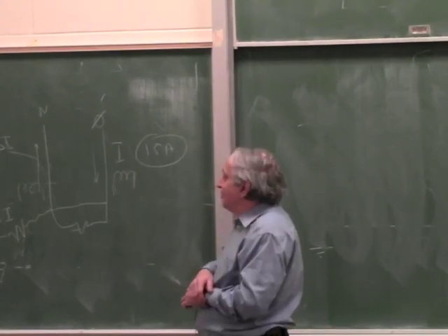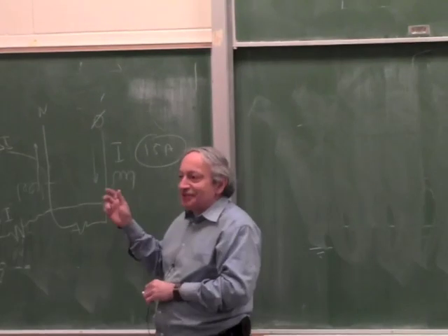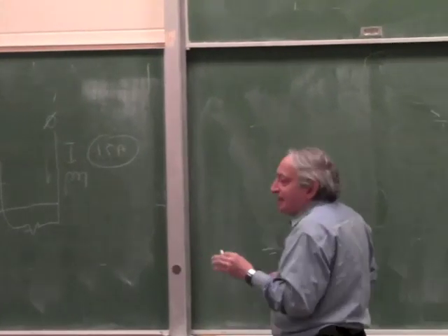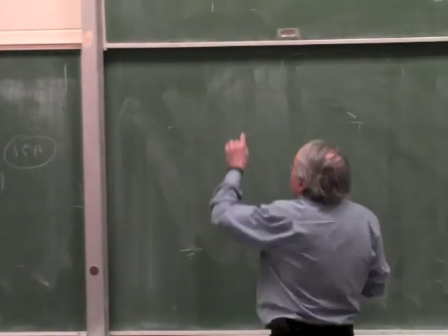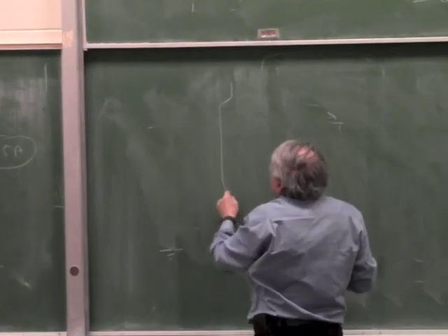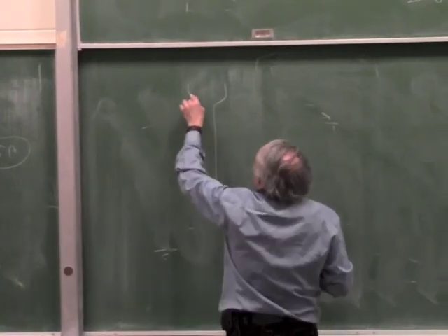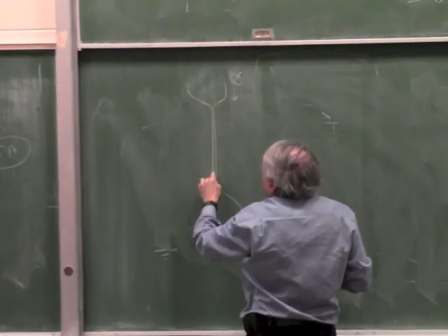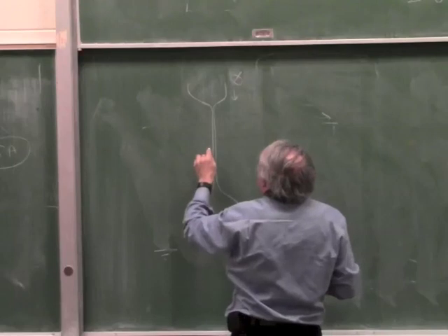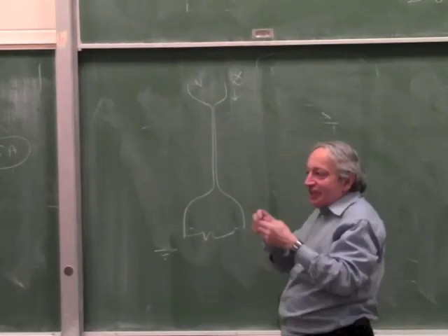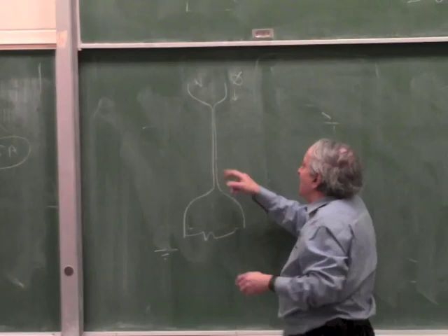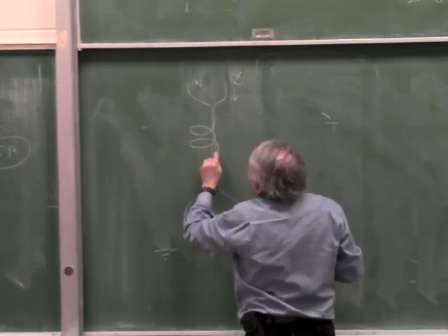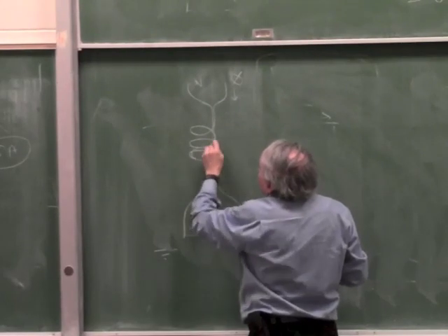Not so simple, because you really want to measure currents here, so it's not so simple to set up a Wheatstone bridge. But I think the way it's done, which is a bit simpler, what you do is you take the current which comes in, this is the phase, and you put it together with the wire which comes back, this is neutral. So you have a double wire, and now you take this double wire and you wind it as a coil, maybe just like 5 or 10 turns.